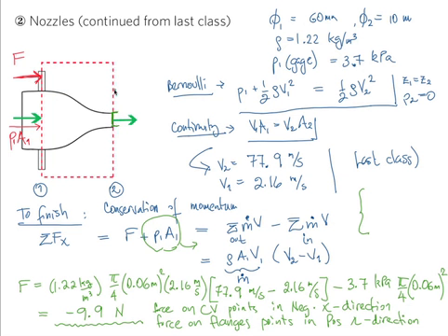So when I'm doing the integral, all of the contribution of this other area is 0 because there's a v dot n, and v is 0 in this part. It is only non-zero in this section here, the exit of the jet, and is only non-zero in the actual section of pipe that is feeding the nozzle. That's why.